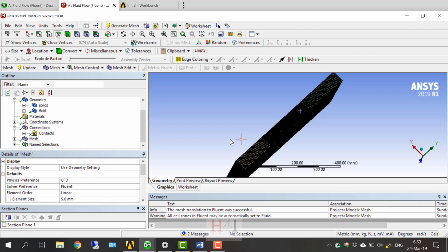So this way I will find an interface with the name of the first heat sink, so I can click on it and get the heat flux. If you select all these interfaces in a single surface, you will find it defined in Fluent as a single surface, so it will be harder to find what you want.